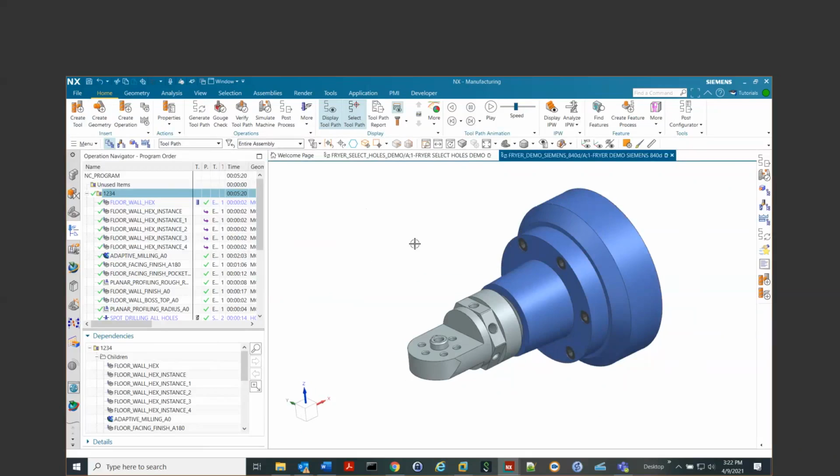How is the collision check detected before it is positioned? I'm assuming, I don't know if he's asking about on the machine or in NX. Yeah, in NX, we tell what pairs we want a collision check, and then give it a within reach. So if I say the holder to the part within 2 millimeters, if you see that, flag it as a collision. It doesn't happen before motion; it happens with the motion. In my world.